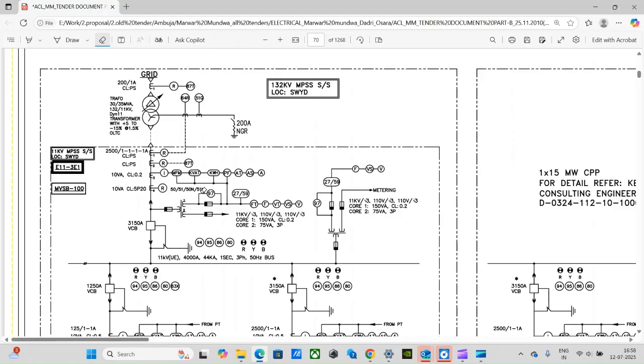As an electrical design engineer, we need to know these symbols. I have already prepared one video for these symbols and their meanings. For example, this is the transformer. This is the delta side symbol. This is the star side symbol. This is the CT symbol, for current transformer, and these rounds. This is called R, meaning relay, and these rounds also mean the IDMT relay. The numbers mean the ANSI code. Every code has a different function.